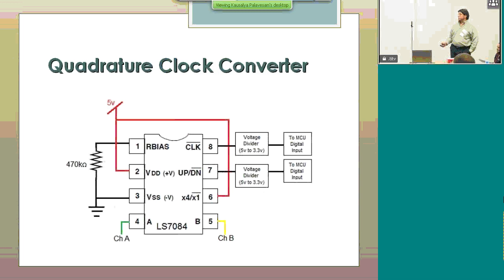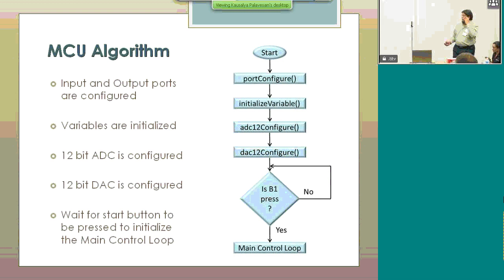And this is a chip. I don't know if TI makes one similar to this. It's a chip that gets the quadrature optical encoder output and gives you the counts and the direction of the rotation, so that we use to input the microcontroller with the counts on one side and then the direction on the other side. That's pretty much the flow chart of the starting.